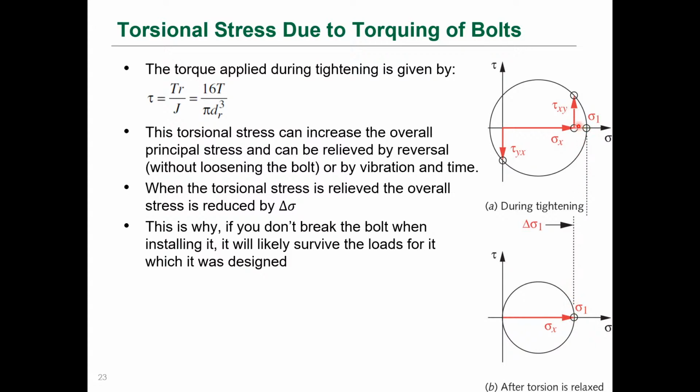So that's why they say if you don't break the bolt when installing it, it'll likely survive the loads for which it was designed, because when you're installing it, you're actually introducing a state of stress that's higher than it'll experience after that torsional shear stress is relieved. Okay,